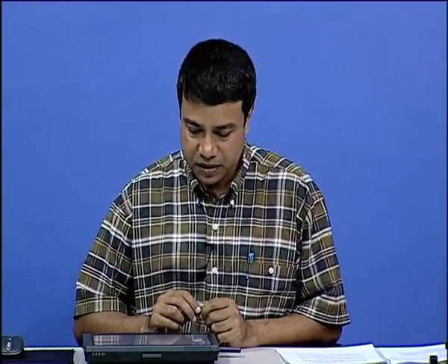So, that was what we saw in the case of high Reynolds number potential flow. Inviscid, the viscosity is equal to 0. Irrotational, that means that the vorticity is equal to 0. There is no circulation within the fluid. So, we had solved the potential flow problems. Of course, when you neglect viscosity, the Navier-Stokes equations reduce from a second to a first order differential equation. And importantly, the momentum conservation equation reduces from a vector equation to just the Bernoulli equation for the pressure.